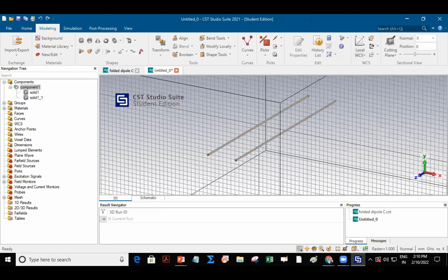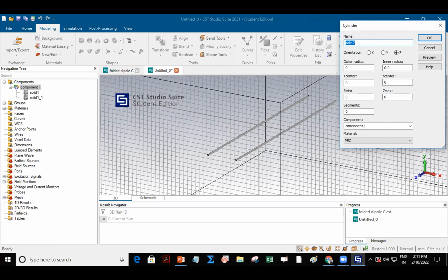So, okay. Gap cylinder is take another cylinder. Orientation is same. Orientation I am keeping it as... how much in Z direction? Or is the diameter coming? 0.4 you said, right? Yes, sir. D by 2 is the diameter. And here we want X center. Z minimum is G by 2. What is the gap coming? 1.1, sir. Minus G by 2 to G by 2.